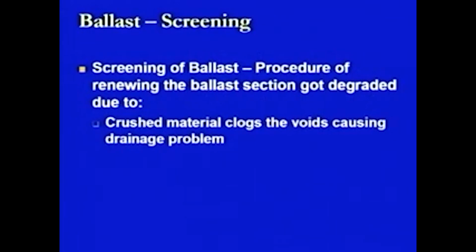Now, there are certain reasons due to which the ballast section gets degraded. They are like the crushed material clogs the voids, causing drainage problems. This is one aspect. Because there is a continuous hammering action from the top, the material gets reduced to smaller sizes, and slowly the voids get clogged by the smaller particles, and when the voids have got clogged, the water cannot be drained out. So, if there is a saturation or flooding of the water, or stagnation or ponding of the water on the side,